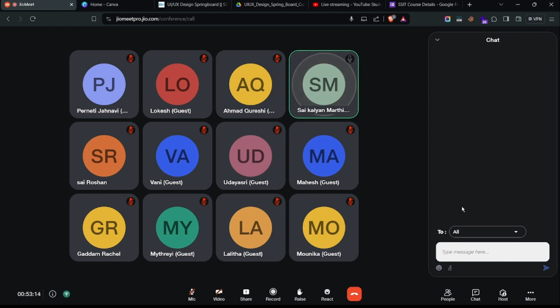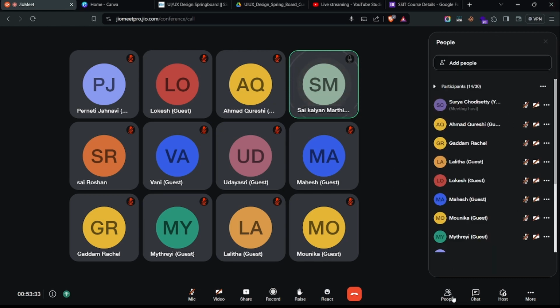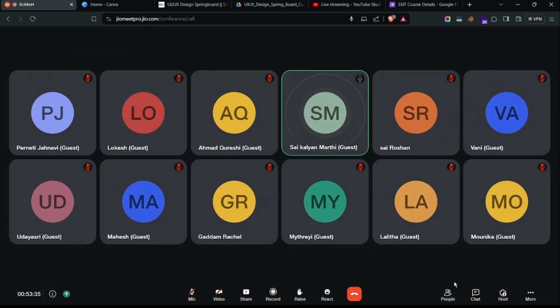And one more thing you asked: while designing hardware, do you choose the circuits based on data sheets? How to develop bug-free hardware? See, one thing I can say, the first version is never bug-free. That is from my experience. While designing the hardware, we go through the data sheets and the application notes given by the vendor.